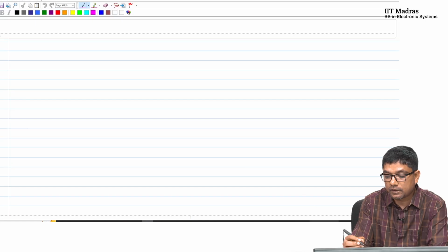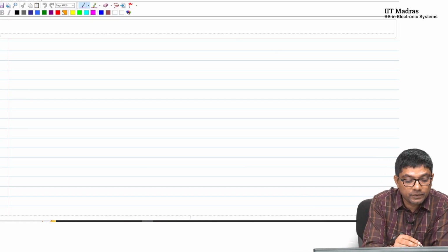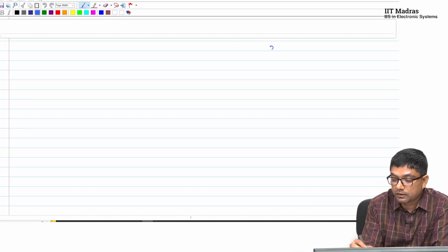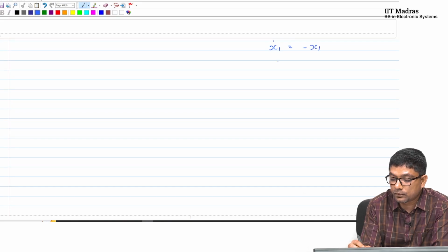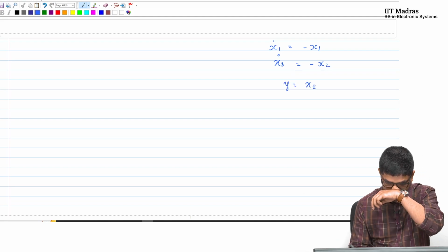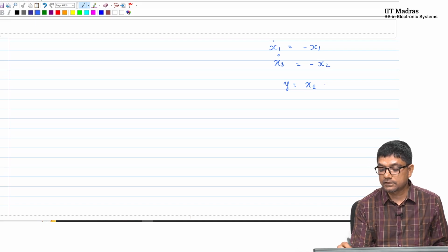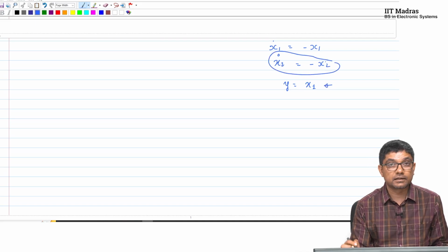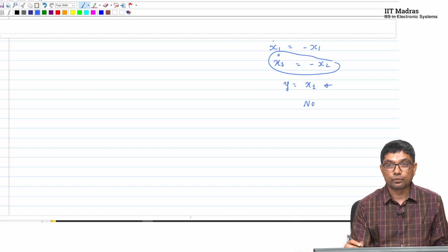Look at now a system maybe of the form x1 dot is negative of x1, x2 dot is negative of x2. Do not worry about inputs for now, and y is just x1. Okay. So, by measuring x1, can I get some information on x2? The answer is no, right.